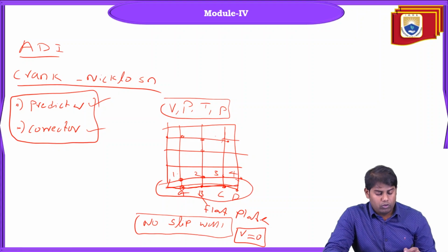No slip, the meaning of no slip is, when the flow propagates over a solid surface, the first fluid layer will get contact and attached to the wall because of the friction, or the cohesive and adhesive nature between the wall and the flow.